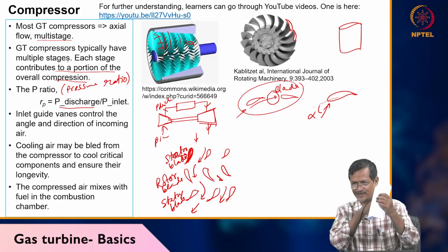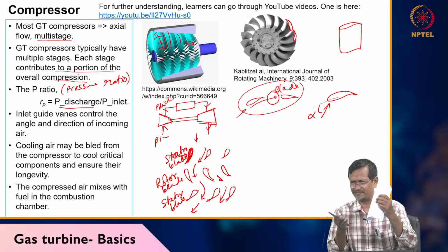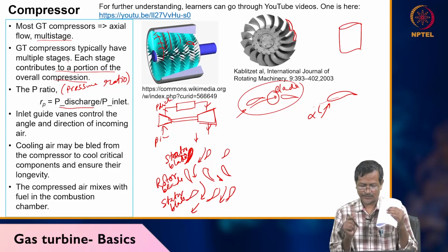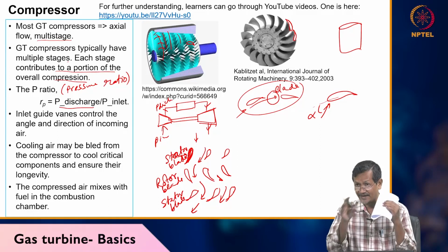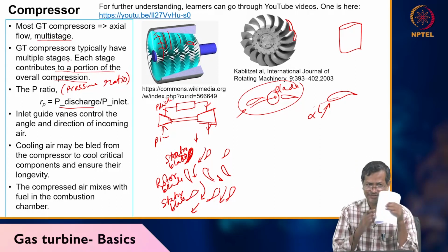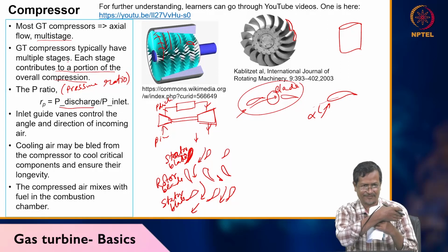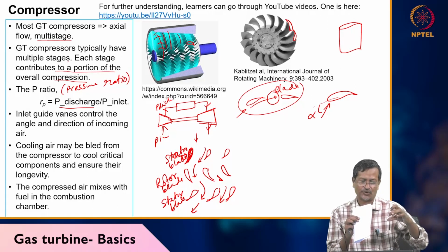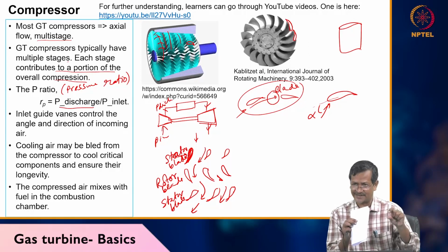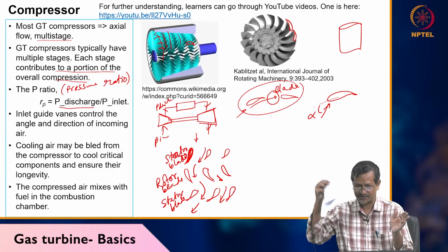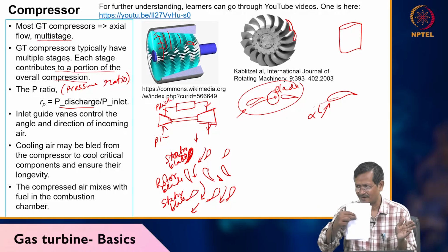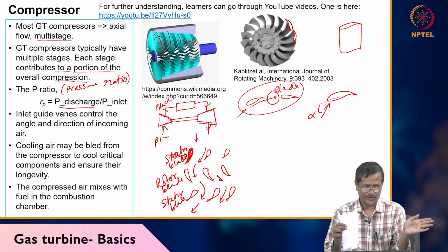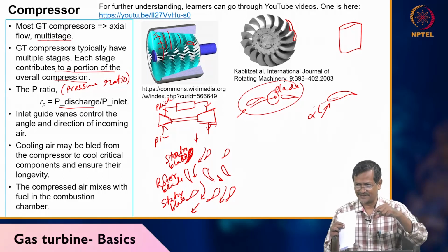So a turbine rotor will have one blade, two blades, three, four, five blades, 36 blades. Many numbers of blades are possible for different types of turbine. The stator blade will give the angle only, it will not harness any energy. It is a fixed blade, it directs the fluid. Now I will have the rotor blade here, which will harness energy, so it must get that proper angle. The stator blade's purpose is to give the proper angle, not to harness any energy.